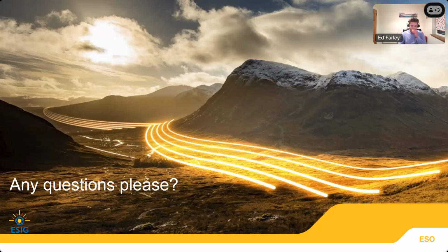Do you treat inertia from synchronous machines and synthetic inertia responses from IBRs differently? We don't, at the moment. Okay, that's very simple. Yeah. With the first grid forming batteries going online as part of Stability Phase 2 this year, we will get a lot of learnings from that, but at the moment we treat them the same.